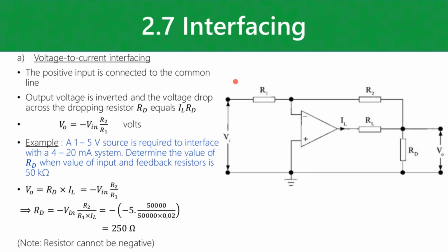But anyways, we can describe the output voltage as you would with an inverting amplifier. In this case, it's negative because it's inverting, so it's going to be the negative of V in multiplied by the ratio of your feedback resistance to input resistance. That's basically this part of the circuit.